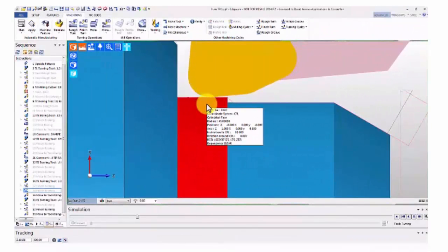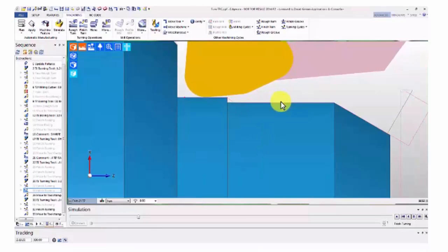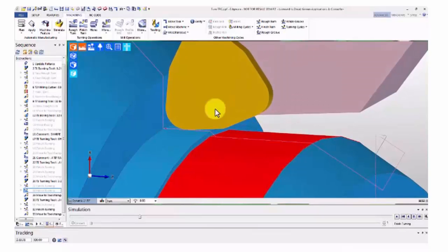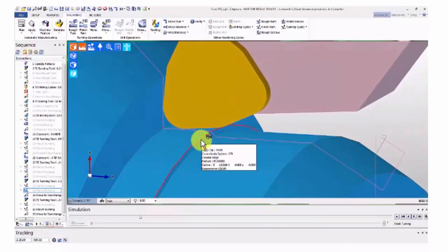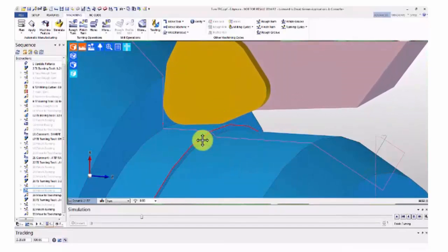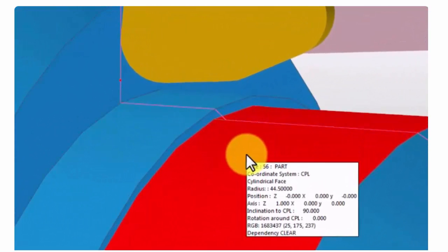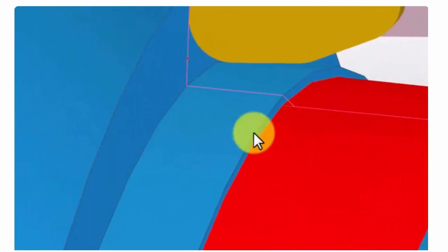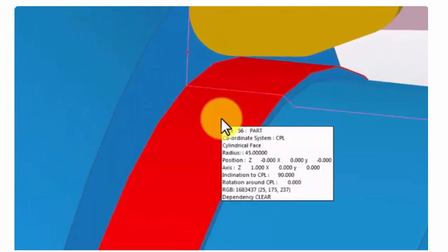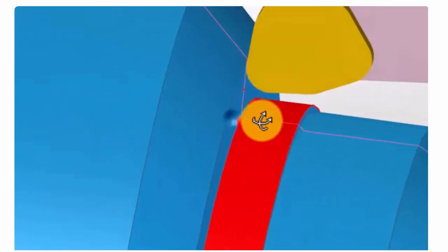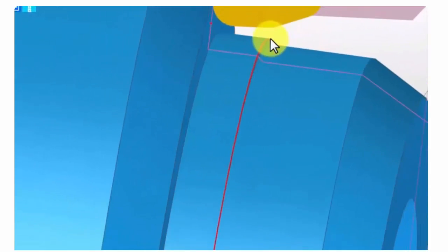But if you just wrote that as a simple CNC program, so you'd have a Z figure to this distance down here, whatever that is, so you'd be going to Z minus 15.310 from 44.5, which would be 89, you would then go to 90, which is just a 1 mil difference in diameter, half a millimeter in radius.